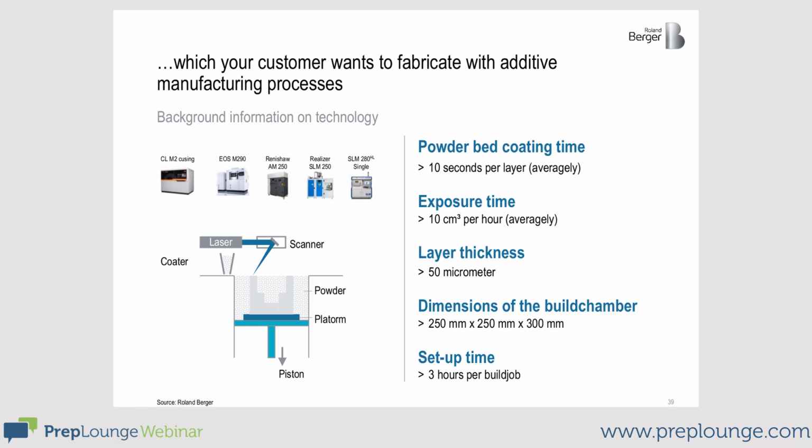This procedure has two advantages, and there are two use cases when it really makes sense. During existing processes, I usually need tools or have to write a program for the machine, so the machine can handle my piece after all. For example, when milling. Here, I don't have to do this. I have the possibility to create a component without any tools, just with my CAD data, which means the 3D images. That's always good when I only need a number or a small number of units.